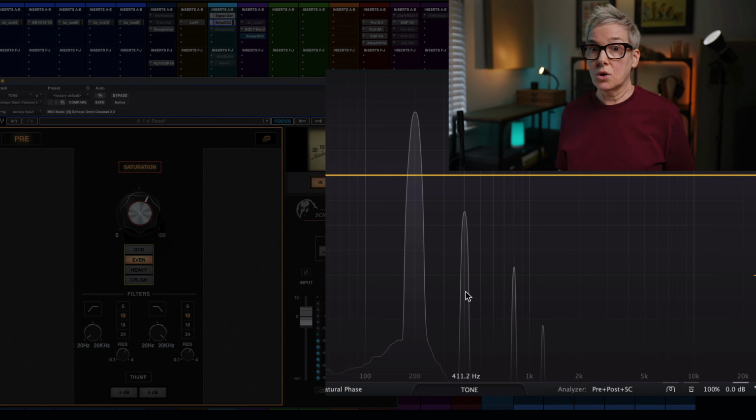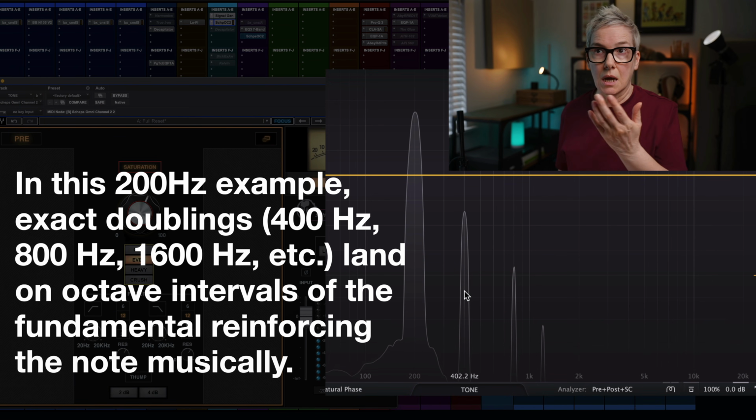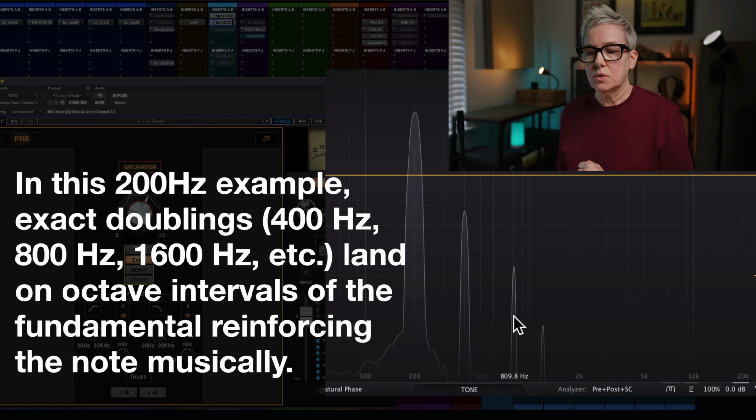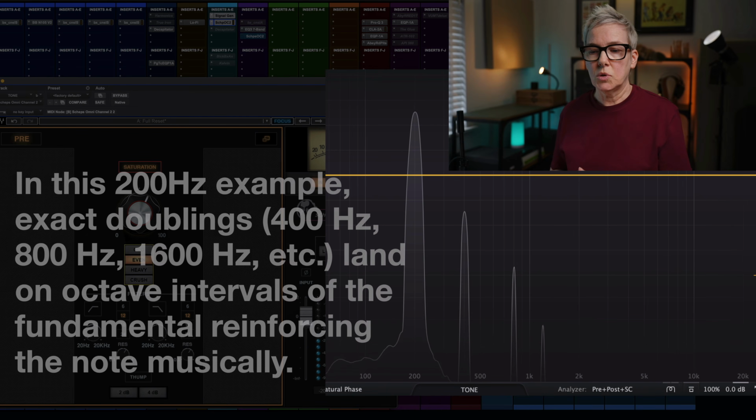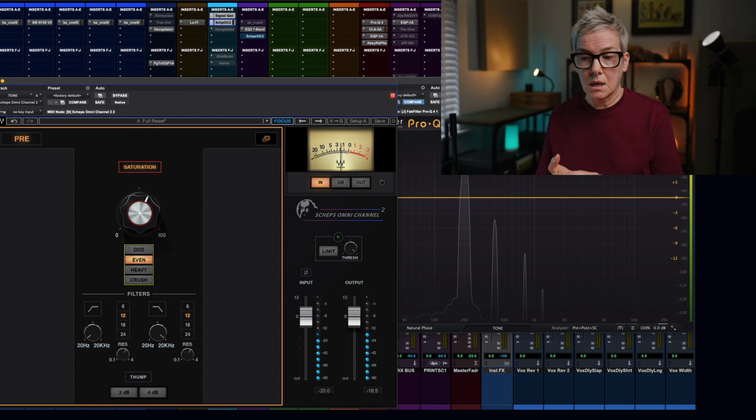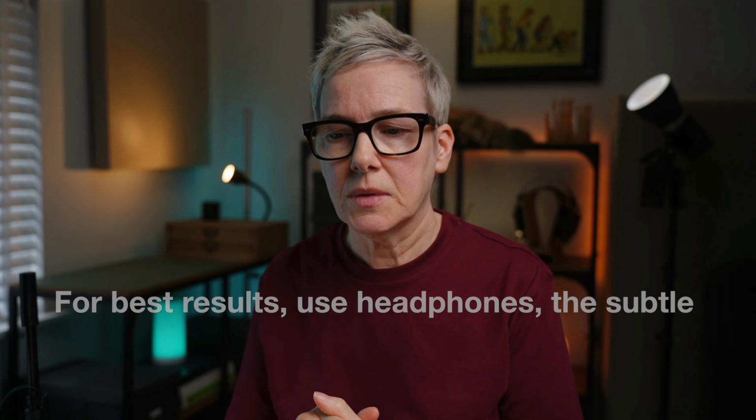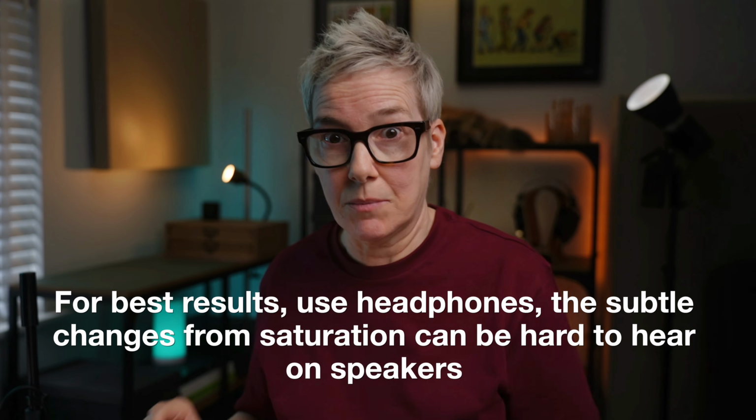What about even then? So here we have second order harmonics. We see a 400 Hz tone being added, and then fourth order is 800 Hz, and then lastly we're getting one here at 1.2 kHz, which is our sixth multiple. So I hope that makes sense mathematically speaking. So how do these actually sound? Odd harmonics have a brighter, edgier tone to them, and even harmonics have got more warmth and fullness. So let's listen to a couple of audio examples of that.